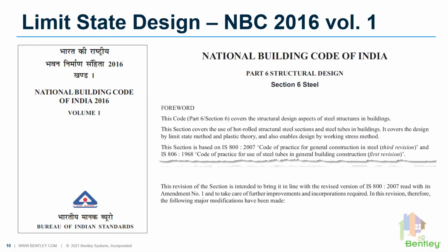Though the latest version of the steel design code is IS 800 2007 with 2012 amendment, there is another published Indian code which provides design standards for steel members and is more updated than the IS 800 code. I am talking about the latest NBC 2016 code. In this code, under section 6, steel design as per the limit state method is described.